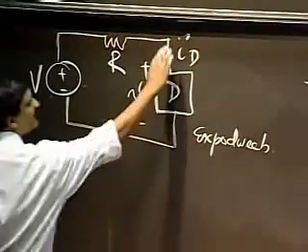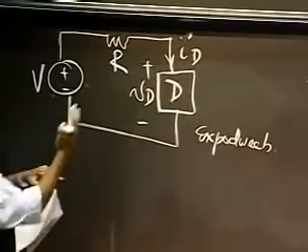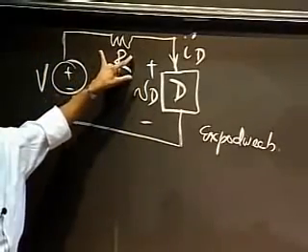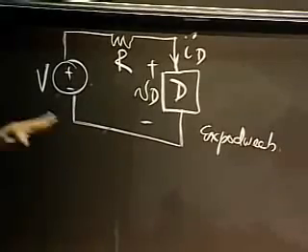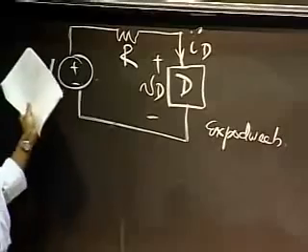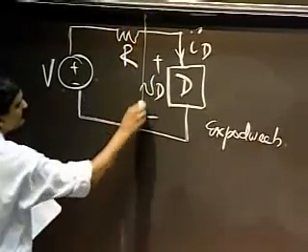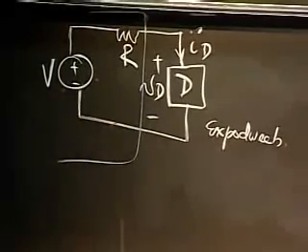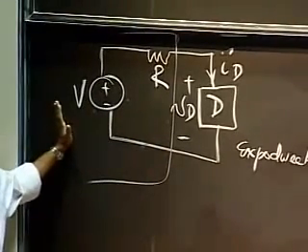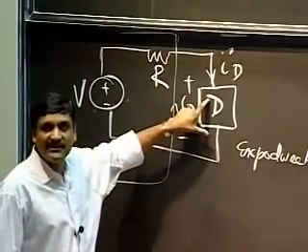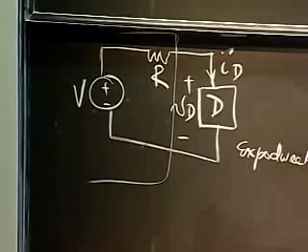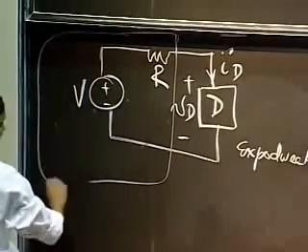In particular, if you look at the nonlinear device here, facing the nonlinear device is a voltage source in series with a resistor. The reason I say this is an incredibly important pattern is the following. Notice that if on the left-hand side I had any linear circuit, and I had a single nonlinear element in that circuit, then by a Thevenin reduction that you've learned, you can take this entire mess.